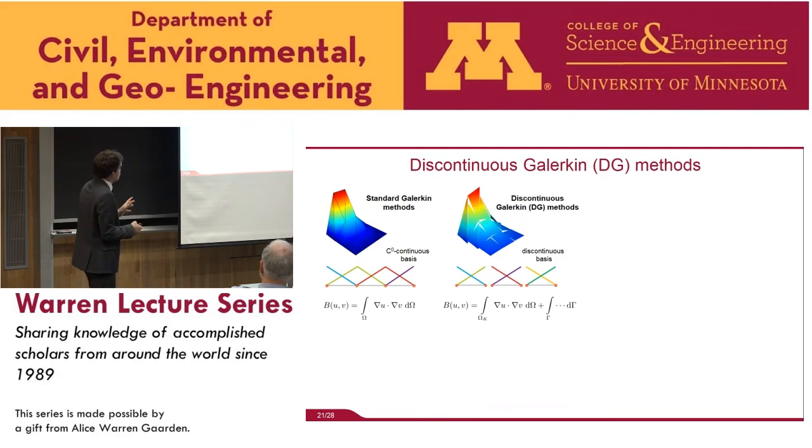That is a restriction for a relatively new class of finite elements that is called discontinuous Galerkin methods. So in contrast to standard Galerkin or standard finite element methods where you have continuous basis functions, in the discontinuous Galerkin method, you have discontinuous basis functions because you start formulating your problem on one single element domain and then derive some element interface conditions in terms of integrations over these element interfaces that tie these elements together.